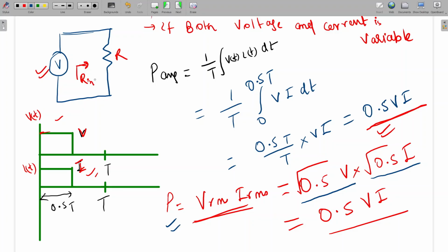See, this is the fundamental average power formula. This I am only applying everywhere. But if one value is constant, we take it outside, which means for the other value we have to take the average. If both values are variable, okay, in that case, for power, we have to multiply V RMS into I RMS. Is it clear? Is it clear to us?